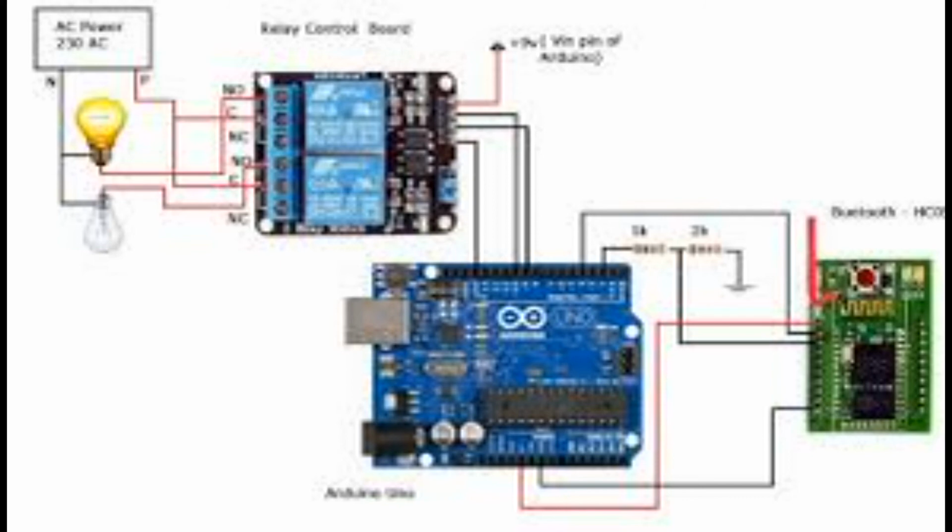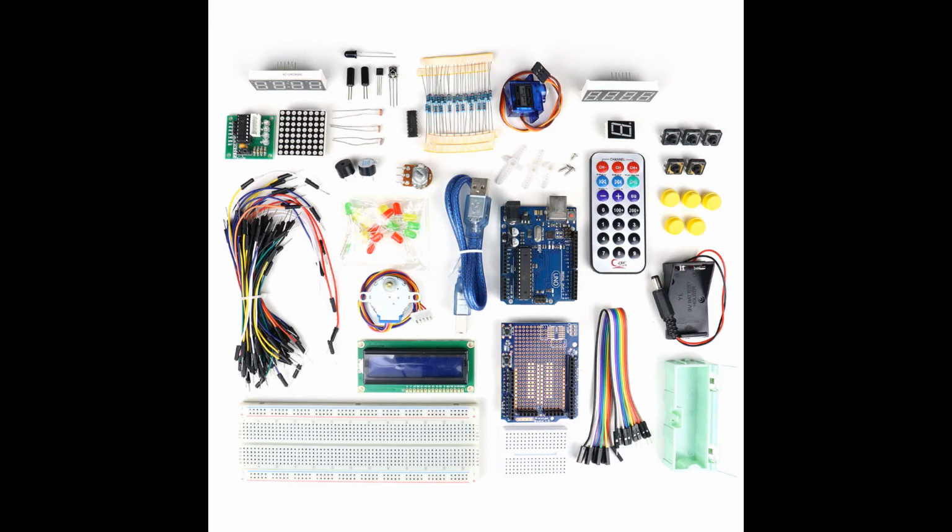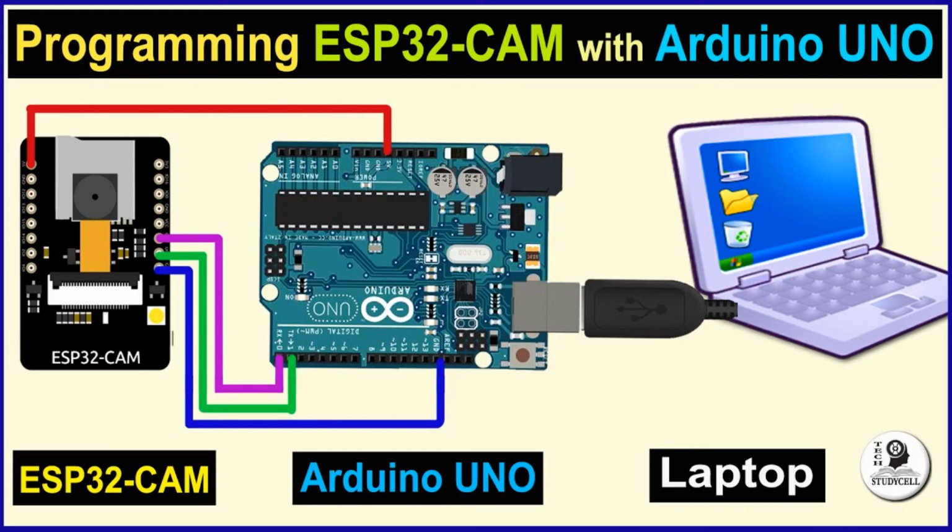via the USB to serial chip and USB connection to the computer, not for serial communication on pins 0 and 1. A SoftwareSerial library allows for serial communication on any of the Uno's digital pins. The ATmega328P also supports I2C, TWI, and SPI communication. The Arduino software includes a Wire library to simplify use of the I2C bus.